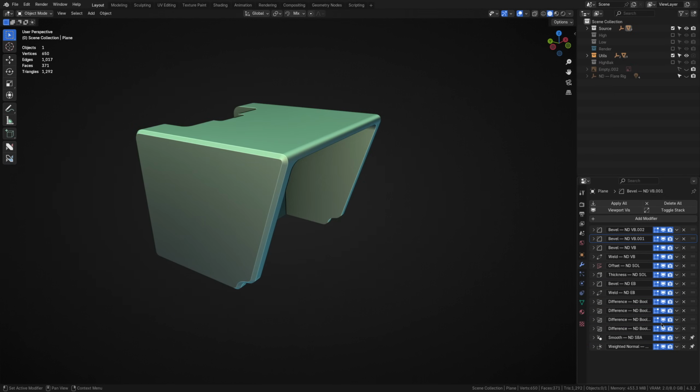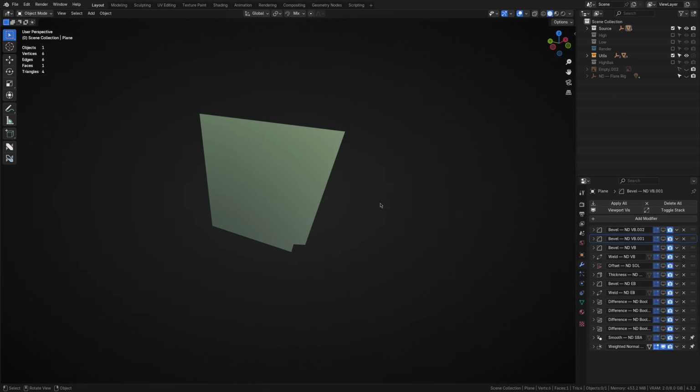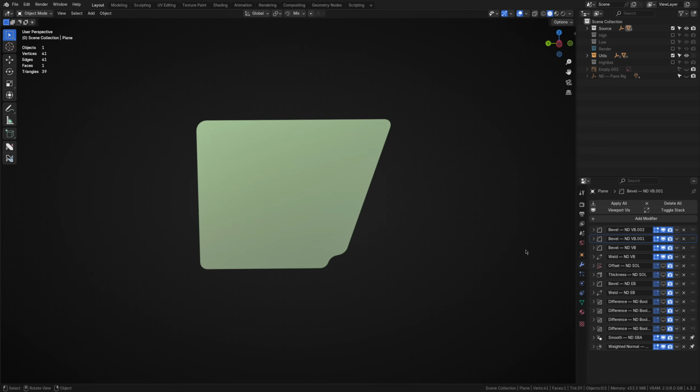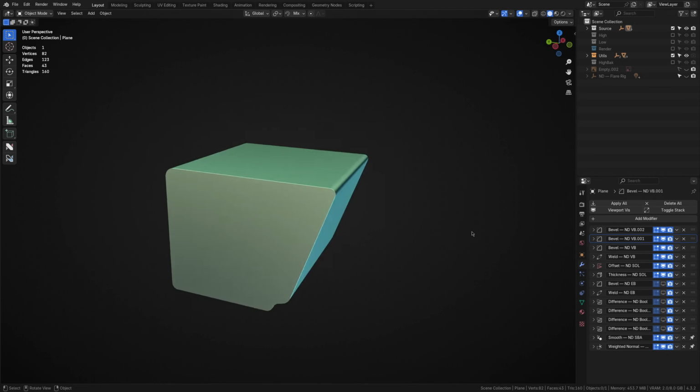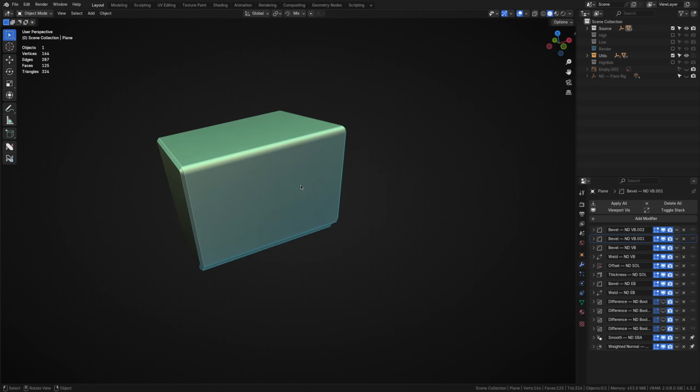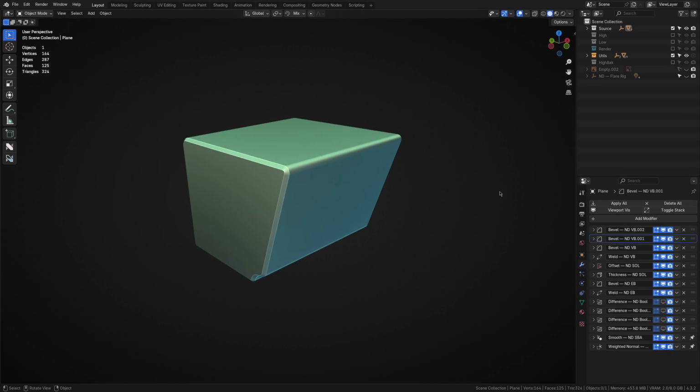Here's the sketch I created. To further enhance it in a similar way to the batteries, I added a few vertex bevels. I then extruded it. I then added an edge chamfer on either side. I then cut out a large hole for the screen.